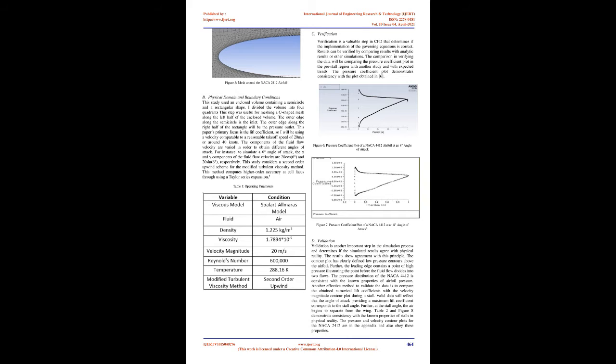For instance, note in figure 2 that the leading edge of the airfoil contains a stagnation point where the velocity is equal to 0. The fluid flow is diverted into one segment above the airfoil and one segment below the airfoil. Above the airfoil, the flow is pinched together and flows faster than the flow below the airfoil. This is evident in the velocity magnitude contour plot and the streamlines displayed in Figure 2 and Figure 3, respectively. Considering Bernoulli's principle, the airfoil will have low pressure on the top and high pressure on the bottom. This pressure differential causes a lift force.